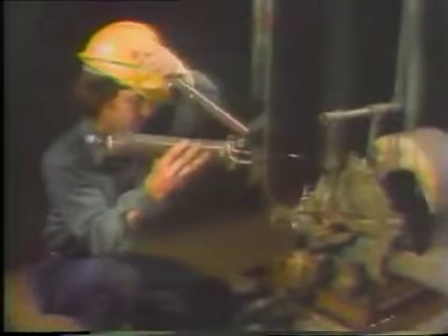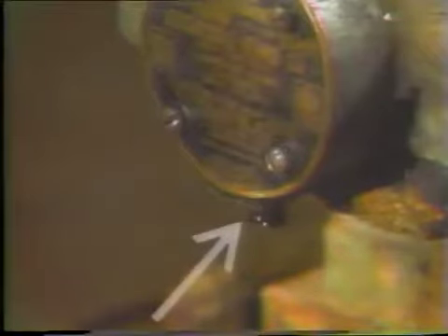The plug is removed so that old grease or excess grease can drain out. Wipe off the grease fitting and make sure the opening is clear. Then, attach the gun to the fitting on the housing. Applying grease while the bearing is in motion helps to distribute the grease more evenly. Grease should be added slowly until it begins to come out of the drain. The machine should be run for several minutes afterwards to make certain that all excess grease has been forced out of the drain. Then, wipe off any excess grease and replace the plug.